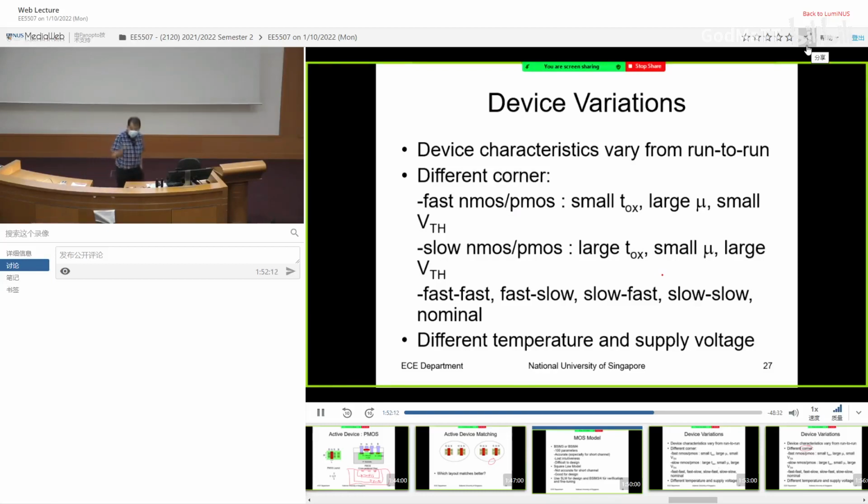There is another approach for the computer literate. Those that are very good at programming, what would they do? The EDA tools nowadays are so good. They have an optimization program. So you can put down the transistor, specify the L, changing from 0.2 to 0.6, and W changing from 10 to 30 in steps of, let's say, 0.5 micron. And then you let the program run. It will try different combinations.